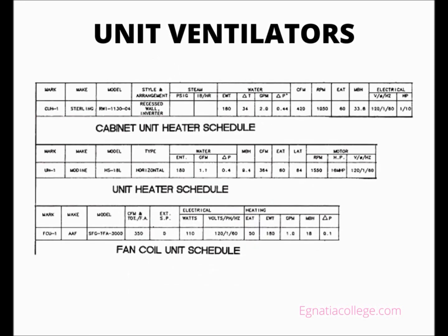This school does not include air conditioning. If it did, the unit ventilators would be supplied with cold water when cooling is called for. The same system of balancing inside and outside air would be used for energy conservation and fresh air, but instead of passing the air over heated pipes, it would be passed over cold pipes. The schedule of unit ventilators would include information for air conditioning.